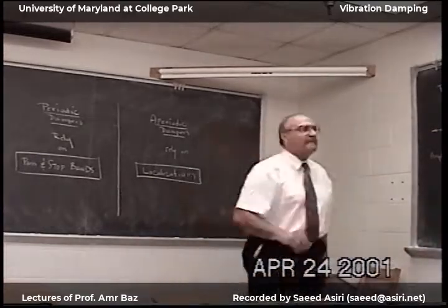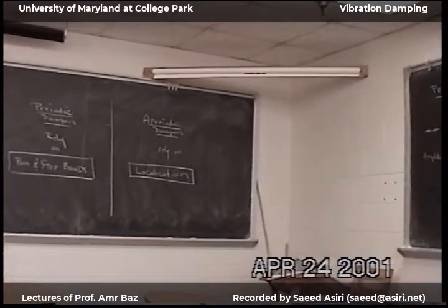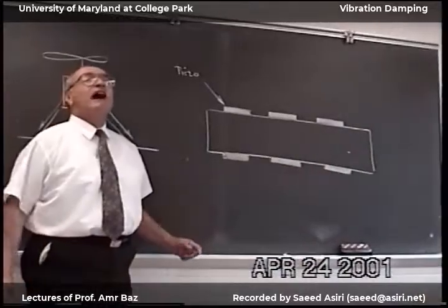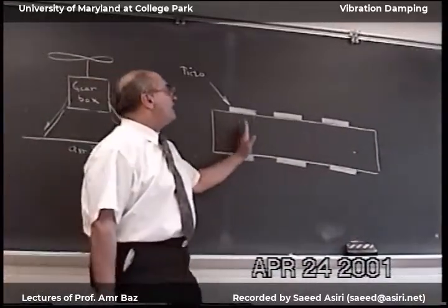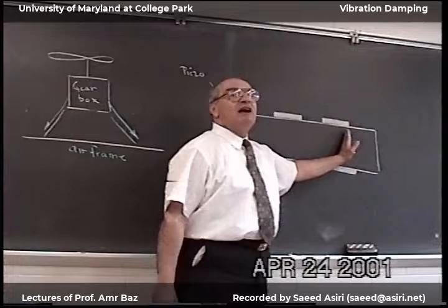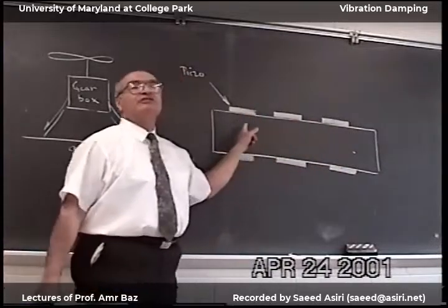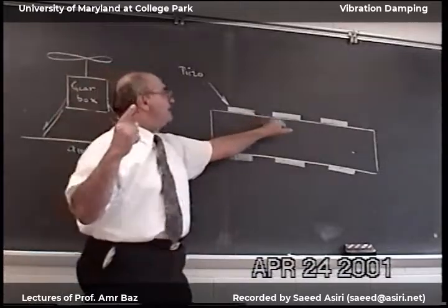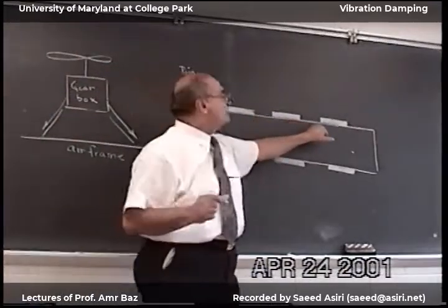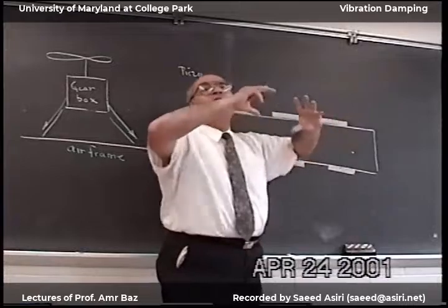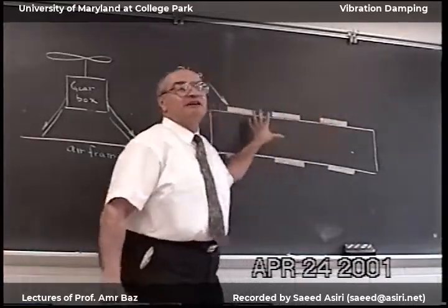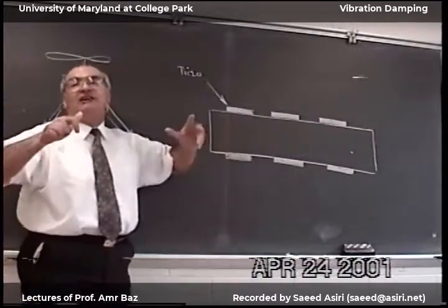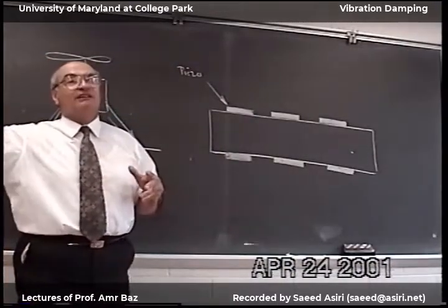So now, if I use these as a shunted network, I can, in spite of the fact that these look periodic, I can come here on each of the shunted circuit, make the resistance here 1, make the resistance here 1.1, make the resistance here 0.9. So I am randomizing the resistances. So what it looks to me mechanically periodic, electrically it's not periodic, it is aperiodic.